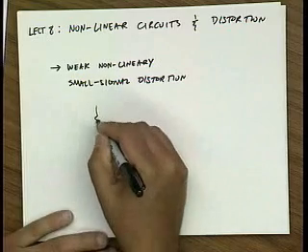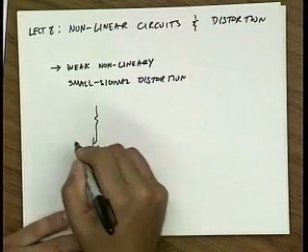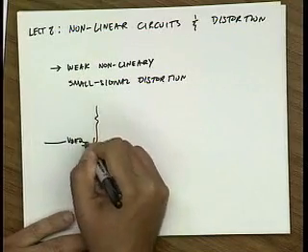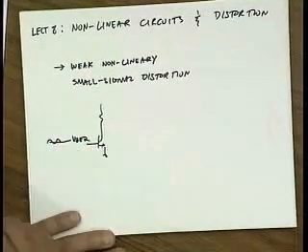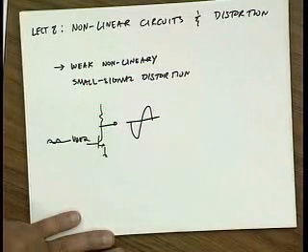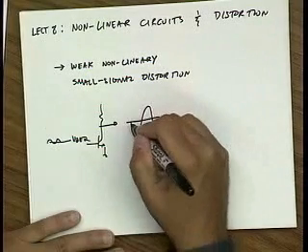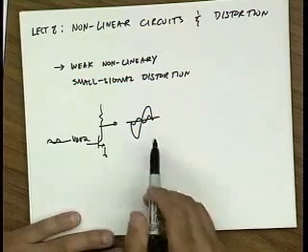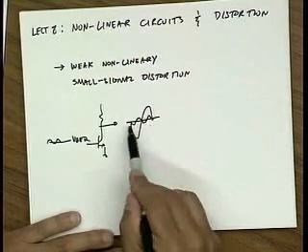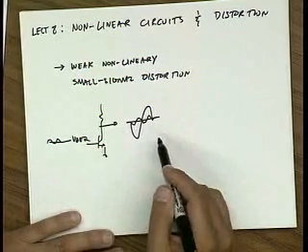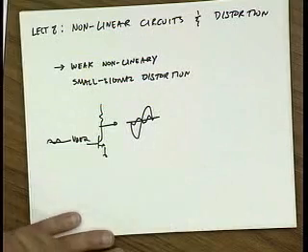If we take a simple amplifier and bias it someplace, let's say VBEQ, we're still putting a relatively small signal on here, and then at the collector we get our output signal, and on top of it we're going to get this harmonic distortion. But the harmonic distortion is a relatively small part. Let's say it's a factor of at least 10 smaller than the main signal.